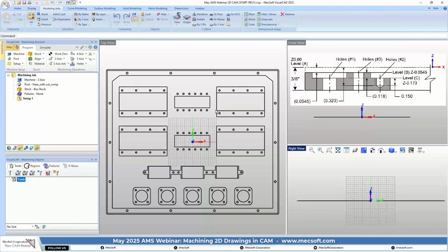For the index 4-axis, that reverts to the requirements of either the 2 or 3 or hole making, whichever operations you do in a fixed orientation on that 4th axis. So for 4-axis fixed, you can revert to the requirements for hole making 2-axis or 3-axis. For simultaneous 4-axis operations, you do need a surface or a mesh to calculate those continuous 4-axis operations.